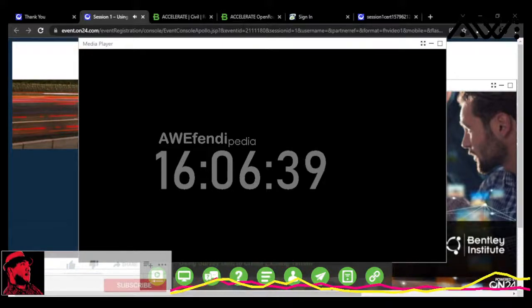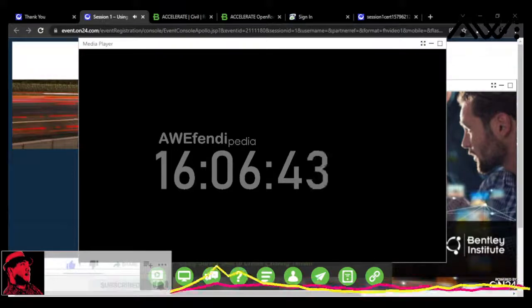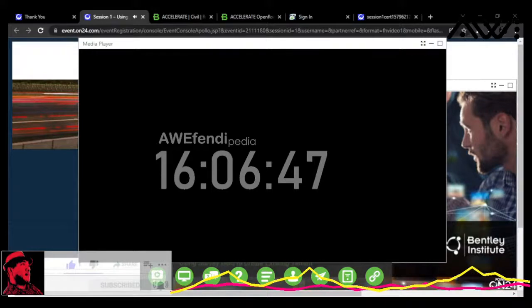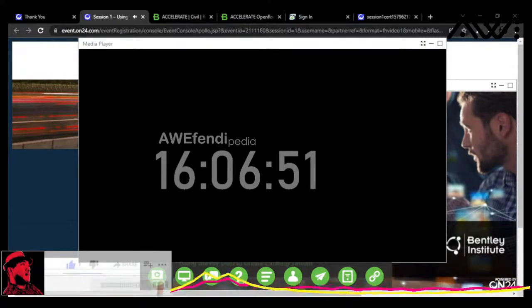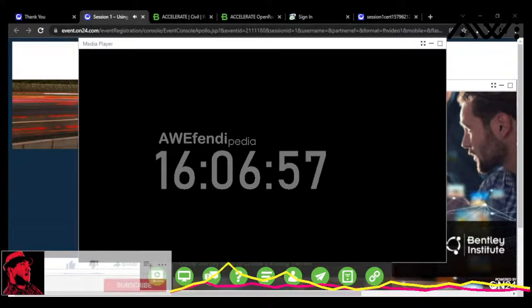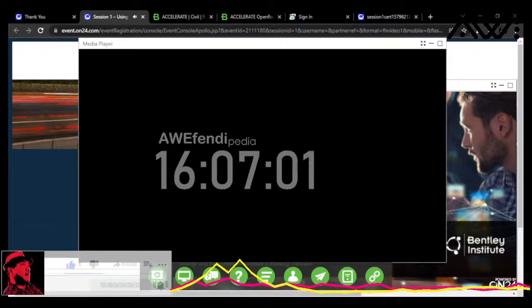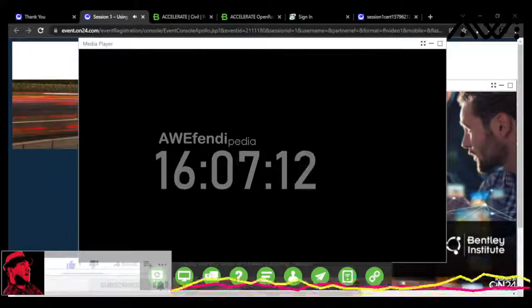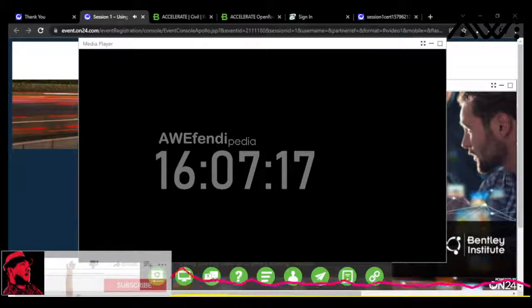I've looked through these before, and really all of the duplicate features in this data set are these types where they're doing a duplicate shot on their traverse point. So I am okay with hitting apply all and just overriding it with the latest shot. I'm going to choose overwrite, hit apply all, and it'll go through and finish reducing all that raw survey data. It's pulling in the angle rights, the slope distances, and the zenith angles to plot those points in the file for me. It's looking at the feature codes to tell it how to draw, and it's looking at the linking codes to build the strings for me. We'll let it finish up here for a second.